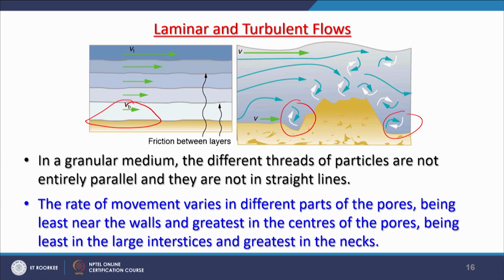That means you cannot withdraw water any further. So, that is why even a common man knows that if you run a tube well for half an hour, give it 2-3 hours of rest and then do it again. So, the discharge should not be high, one, and replenishment time should also be given, so that water comes through the surroundings into the well or near the well in the rock formations, and then you withdraw.